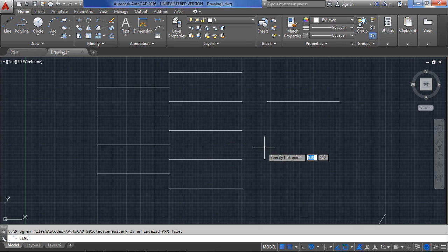Also, I turned on polar assist. As you see, it snaps to different degrees. So this is 0 degrees, 8, 12, 20. It automatically helps me by snapping to these different points. Move it out, and it'll automatically go to 90, 180, 270.